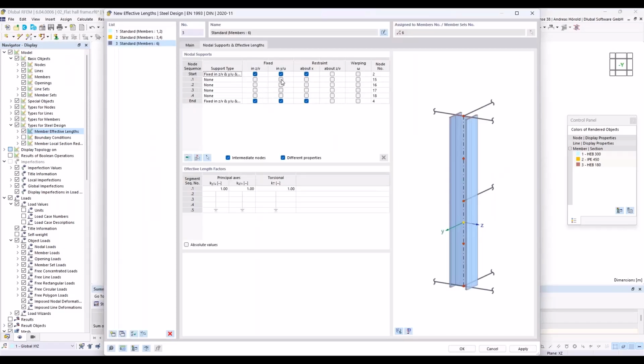Okay, and we would like to fix it in horizontal direction. And I would like to consider that the upper flange is supported. The purlins lay over the horizontal beam. That's why I select all these lines here, and I define eccentricity type at upper flange.